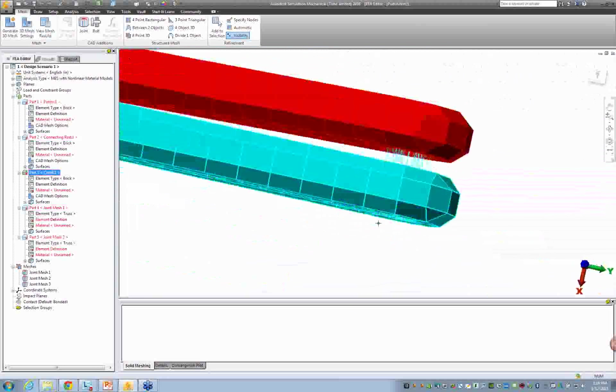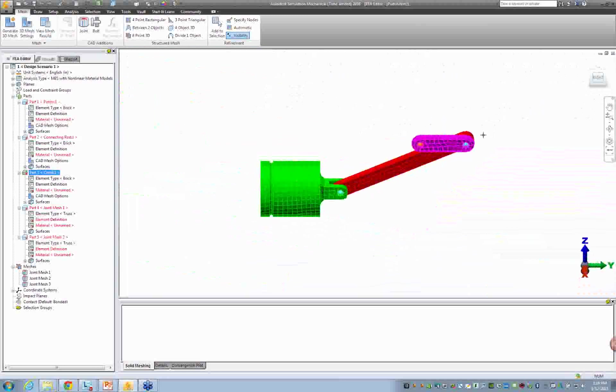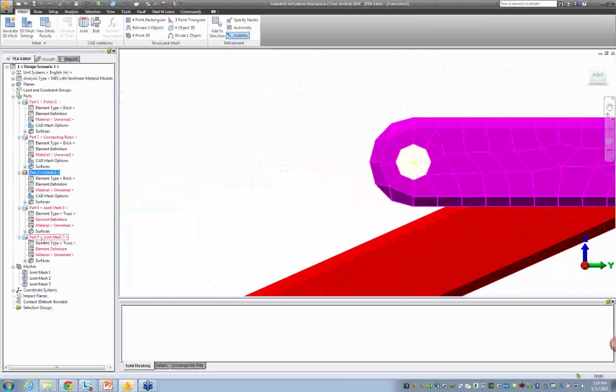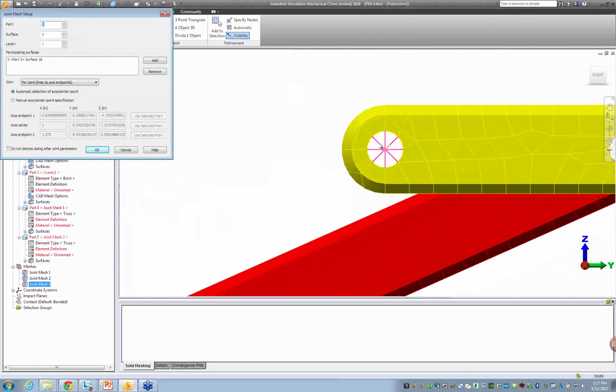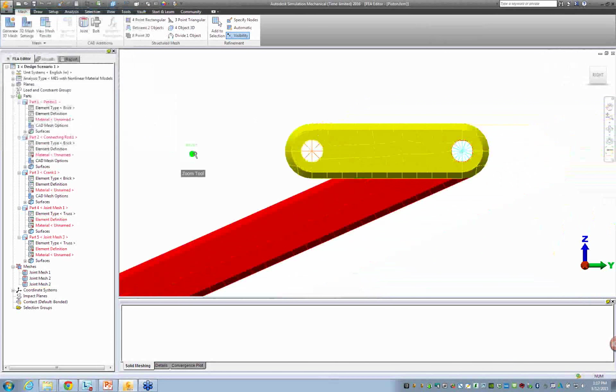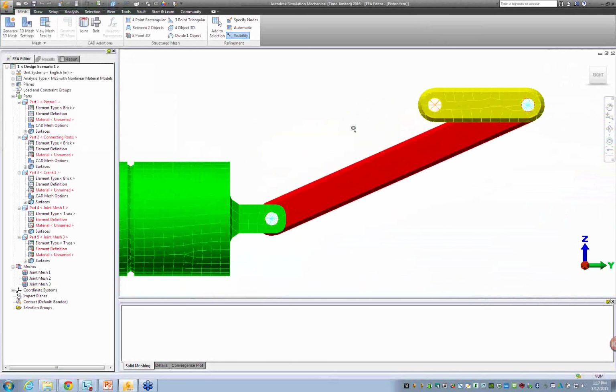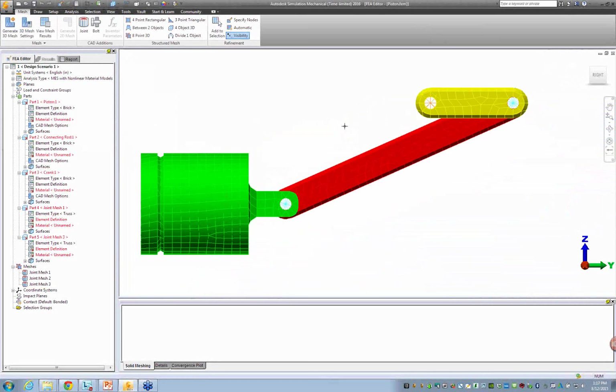We created those joints, and then on the back end we also added a joint to this final hole in the model using the joint creator to be able to select, for example, the center points of this pin joint to be able to add prescribed displacements or prescribed rotations to assign the necessary loads to have this piston move in the positive and negative direction of Y. So now that we took a look at the setup, let's take a look at the results.